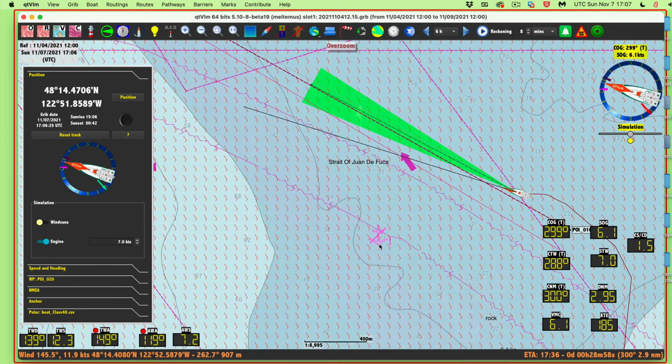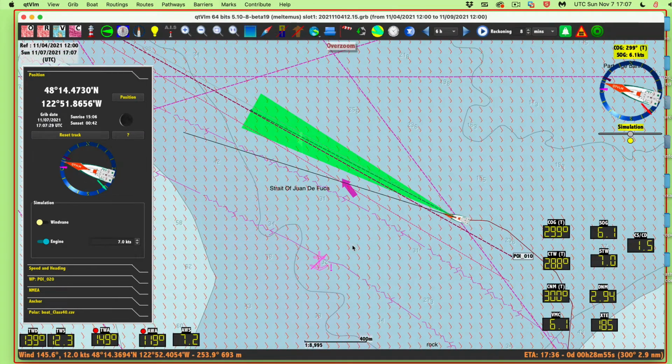All right, so this program is remarkably well set up to do safe navigation. Not only training, we're doing training here, but when you have these kind of tools in your boat, then that's what you would use. And I should point out that most of the good navigation programs have tools like this. Time Zero has a cone like that, but not many. Most only, you have to go to Expedition to get that. But anyway, this is for anti-grounding danger detection. For just plain safe navigation, you just need the COG predictor line and your heading line.